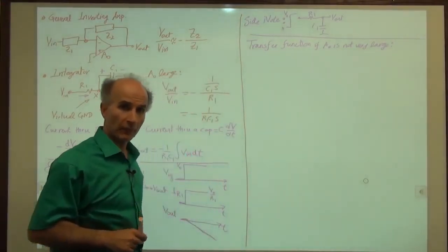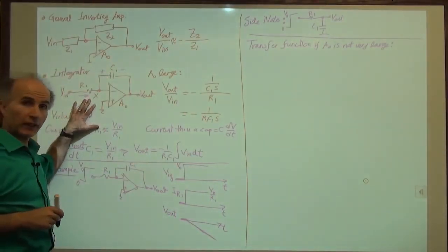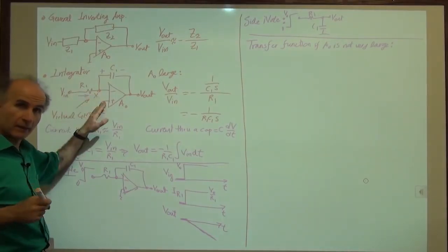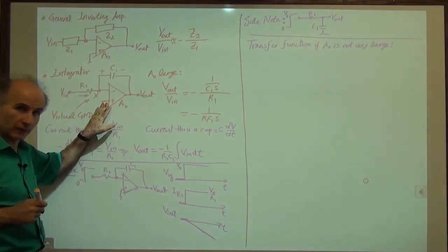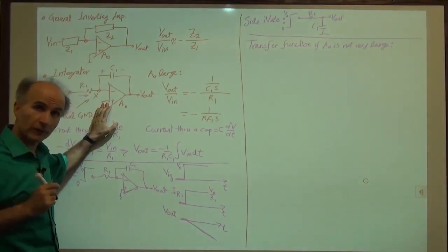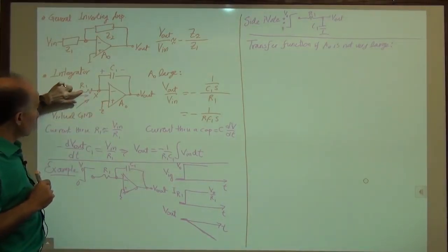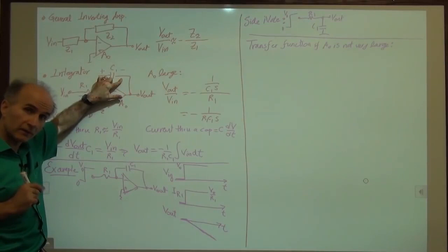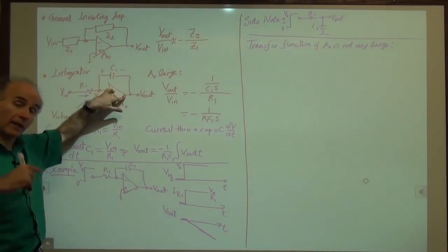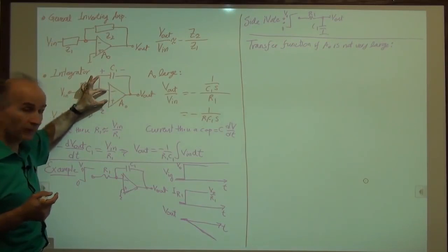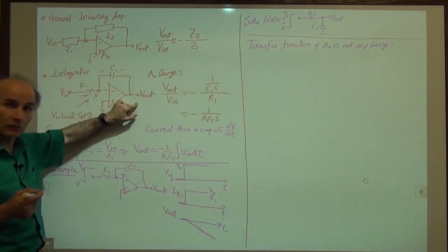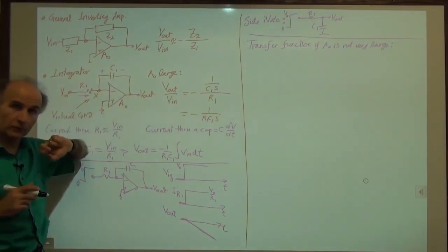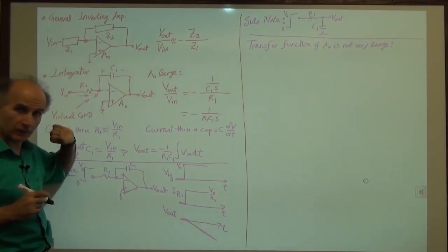Okay. All right, so we have to go back and write some equations more carefully because we cannot say this voltage is very close to 0. It has a voltage, Vx, and then we have to write our equations accordingly. One thing that does hold is that the current going through R1 still has to flow through C1 in its entirety because it has nowhere else to go. And another thing that holds is that this voltage difference times A0 is equal to minus V out. That's the general equation of op-amp that always holds. So with these two principles, we can find the transfer function.